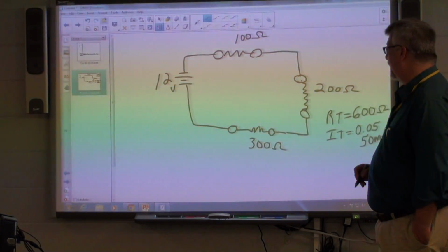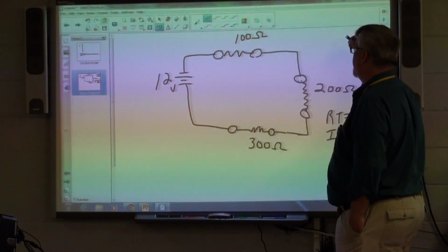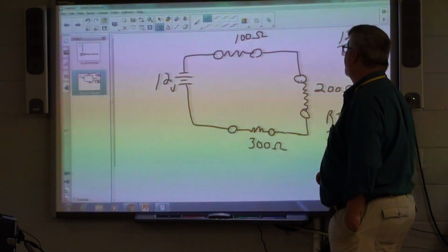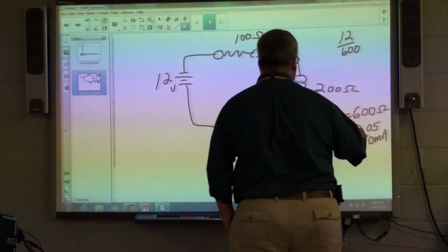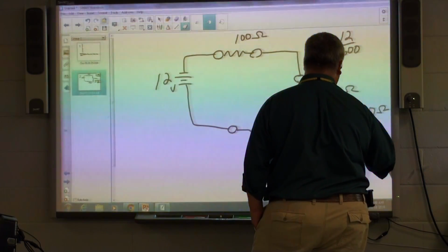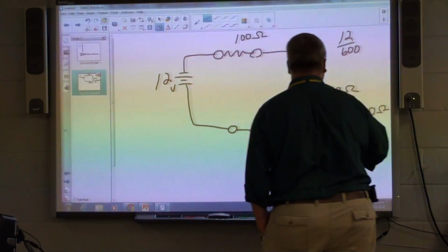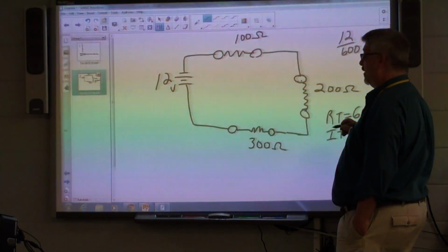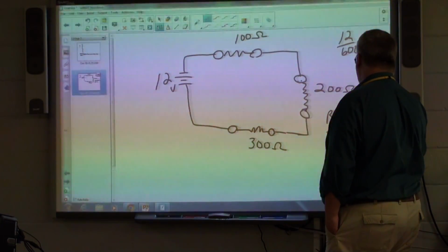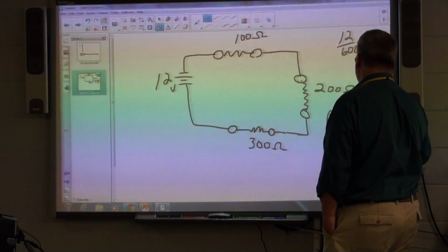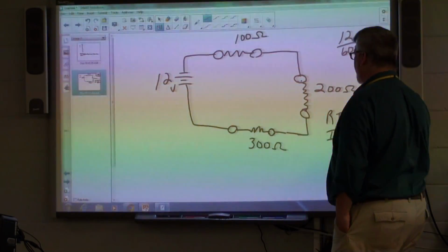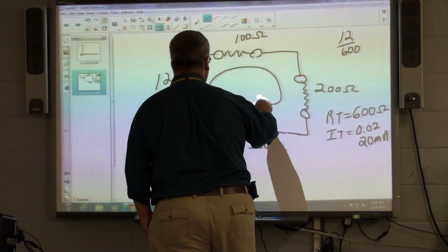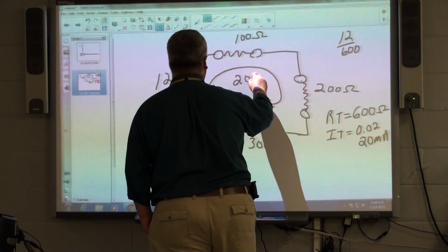Okay. I'm mathing in my head, so it's 600, let's make sure, 12 divided by 6. Y'all want me to correct? 0.02. Yeah. What is it? 0.02. 20 milliamps. I was thinking 12 times 50. So there we go. Now we're right. So through this guy, we got 20 milliamps.